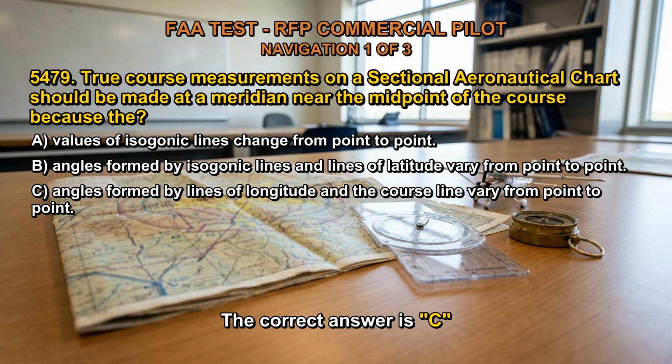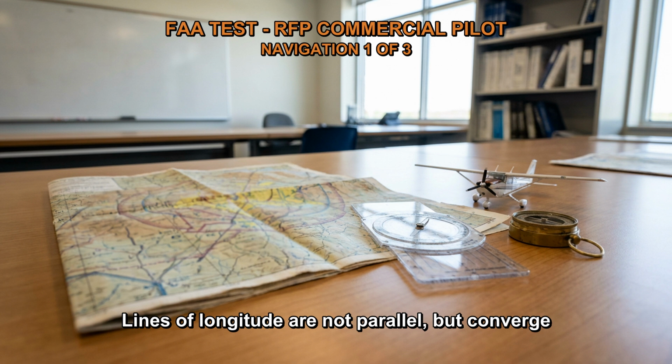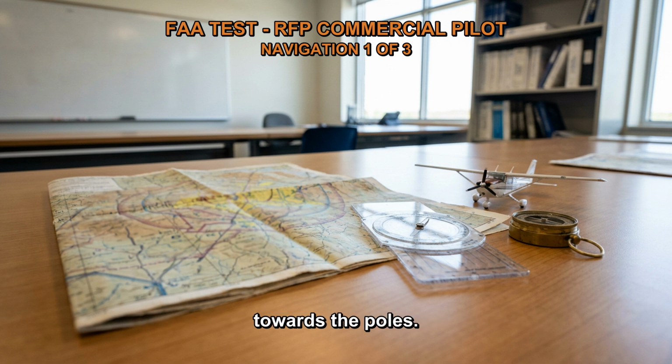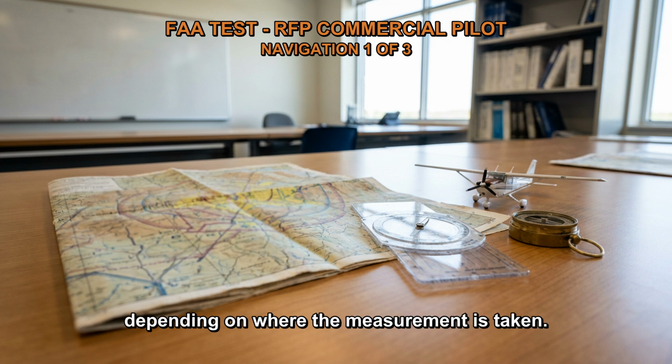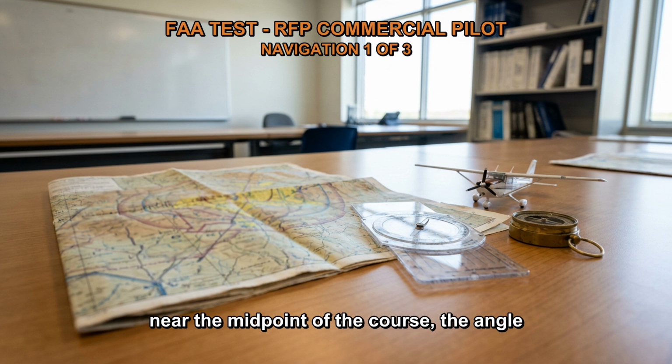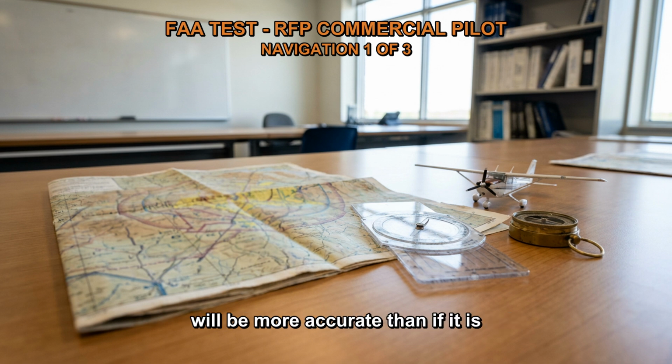The correct answer is C. Lines of longitude are not parallel, but converge towards the poles. This means that the angle between a line of longitude and a course line will vary depending on where the measurement is taken. If the measurement is taken at a meridian near the midpoint of the course, the angle will be more accurate than if it is taken at the point of departure or the destination.